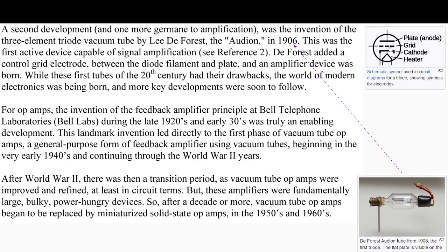And that grid, you tell me whether it should be positively charged or negatively charged. As a basic electricity course, you know that negative and negative repel. It has to be positive, because the intention is to accelerate the electrons going towards the anode. So that's why the grid is timely given a positive charge, so that the electrons coming out of the cathode shoot towards the anode.